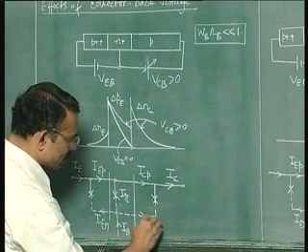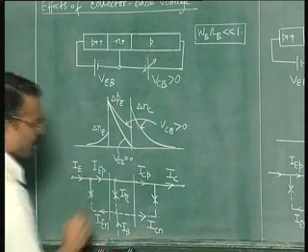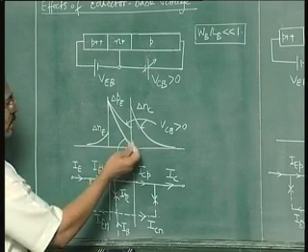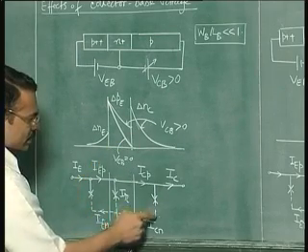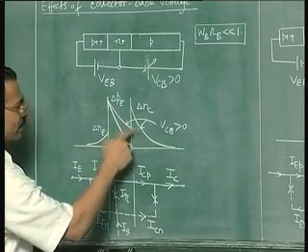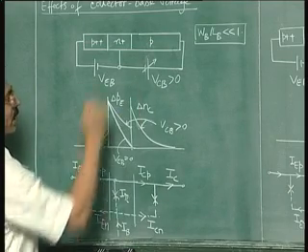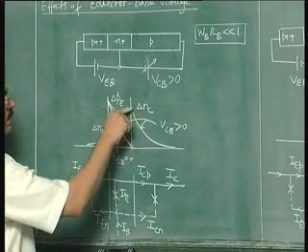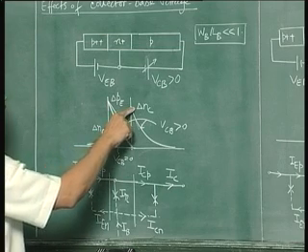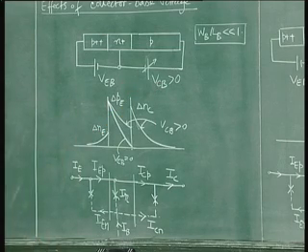So this is your ICN, and as you increase the forward bias, this component will go on increasing exponentially with respect to the voltage, because the boundary value of excess carrier concentration rises exponentially with respect to the forward bias.